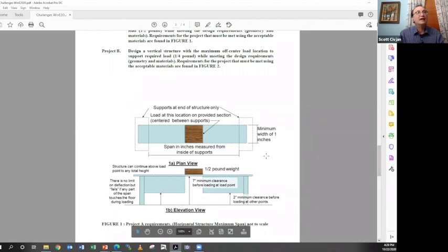Okay, so the first of these challenges, as I said, is trying to get the longest bridge possible. You need to come up with some supports using the material that you have. This bottom part could be a tabletop or the floor, and you're going to build it up and then have a span across. At the center of it, where you're putting the load, there needs to be at least 7 inches from the bottom of whatever you're building down to the ground. At the ends, it needs to be at least 2 inches from the bottom of the structure to the ground. So this can taper or it can be straight, however you want to do it. You could build the entire thing 7 inches and higher, or you could build it 7 inches at the center and then a lower clearance at the ends.